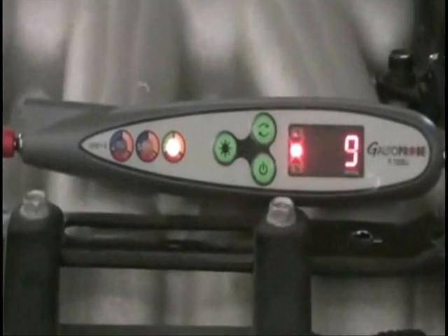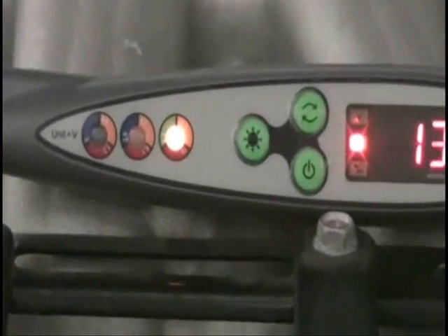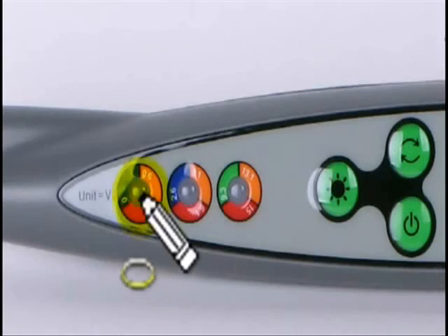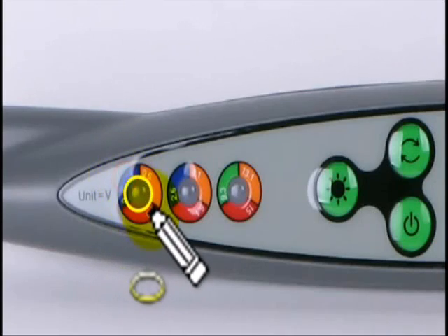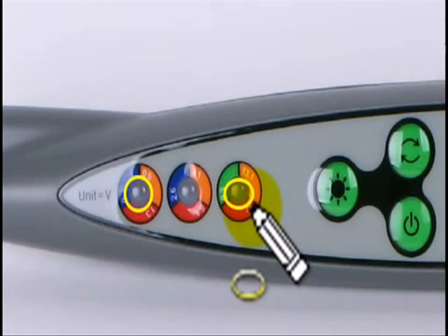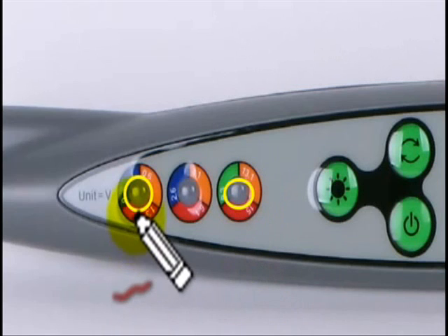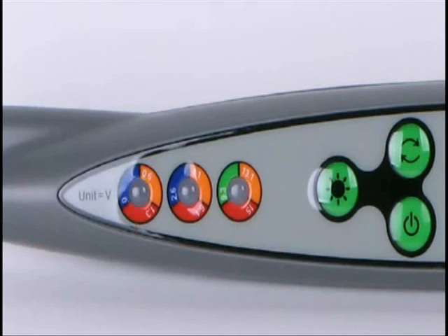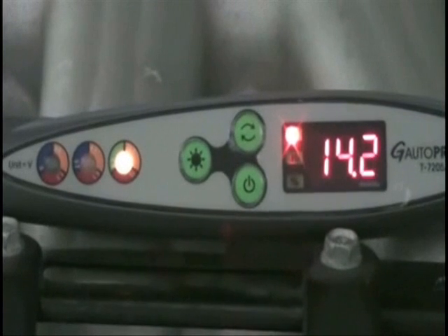Let me check pulse with this probe. This signal is pure injector pulse. This lamp means ground, and this one means 12 volt. The two lamps twinkle in turn. It means that the injector has pulse from ground to 12 volt.